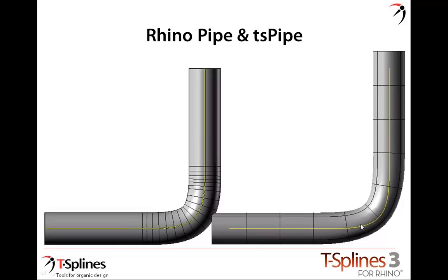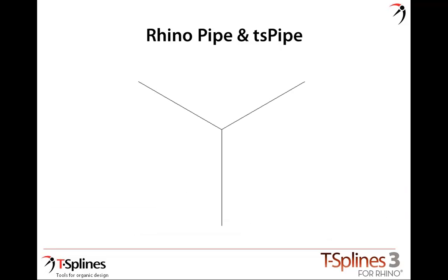This pipe, the T-Spline pipe, the cross-section isn't always circular, even to within tolerance. You can see here as it goes around the high curvature region that it's deviating from this center line, and it's also not the same radius. So we've got some behaviors that, if you're looking for an engineering style pipe, are probably not ideal. It also goes past the end of the curve, and I'll explain why that behavior is the way it is in just a second.